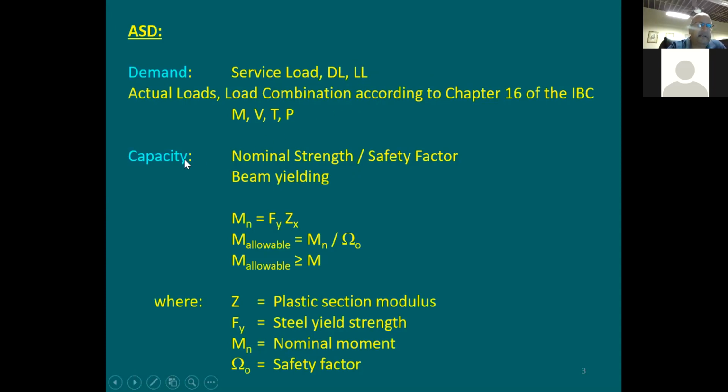When it comes to the capacity here, you're going to have something that we call nominal strength. Nominal strength, and then you take it, you divide it here by a safety factor. Because you cannot just design for the nominal strength to be the same as the total load applied to it, which means if I do this and not use a safety factor, once I approach here the design load, which means I add the dead load to the live load, the structure is going to be reaching its failure point. So this nominal capacity is almost the same as a failure point.